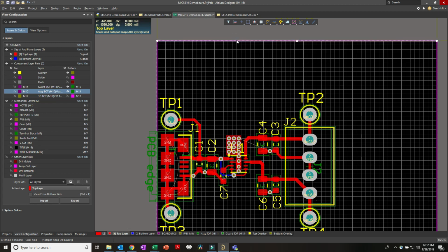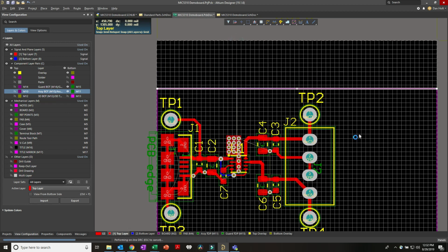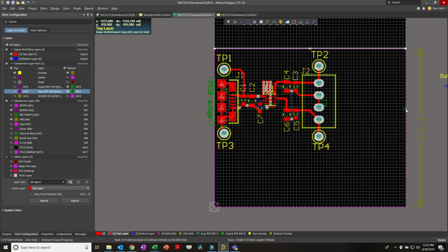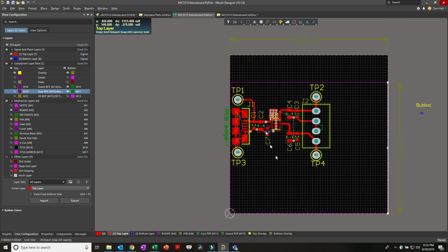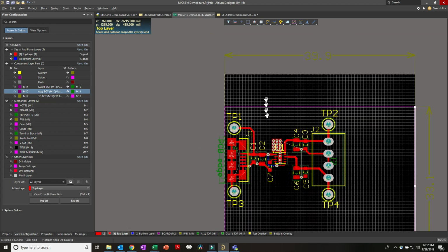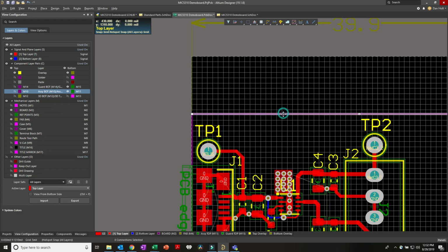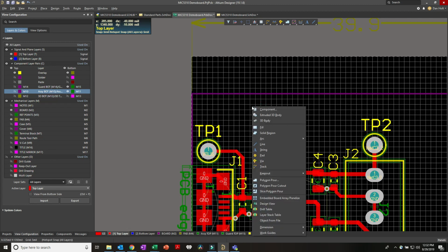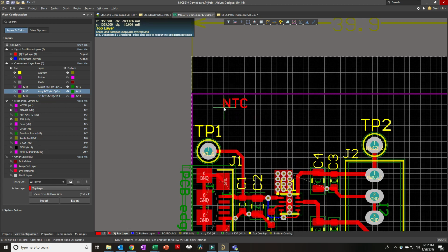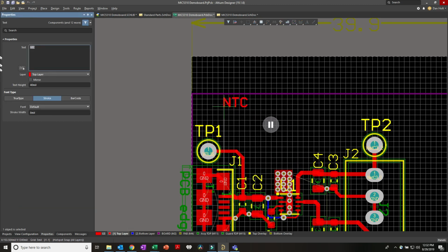And here you can actually see inside the board. Now that we have some vias in there, you can actually fly inside the circuit board and look around. You can see the traces happening. Okay, so anyway, this connector needs to be the right distance away from the edge of the board. So pressing 2, come back to here. You can see where in the footprint it has this PCB Edge statement. So I'm just going to line that up with what the tool says I should use, and shrink this in a bit.